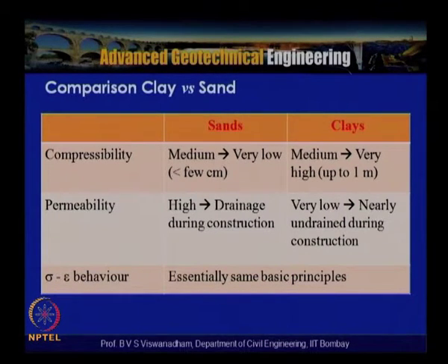In case of sands, permeability is very high, and the drainage happens during the construction. In case of clays, permeability is very low and nearly undrained during construction.